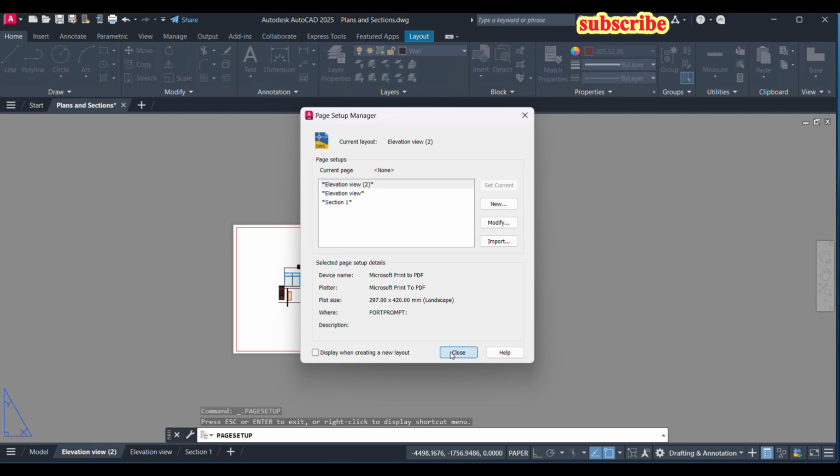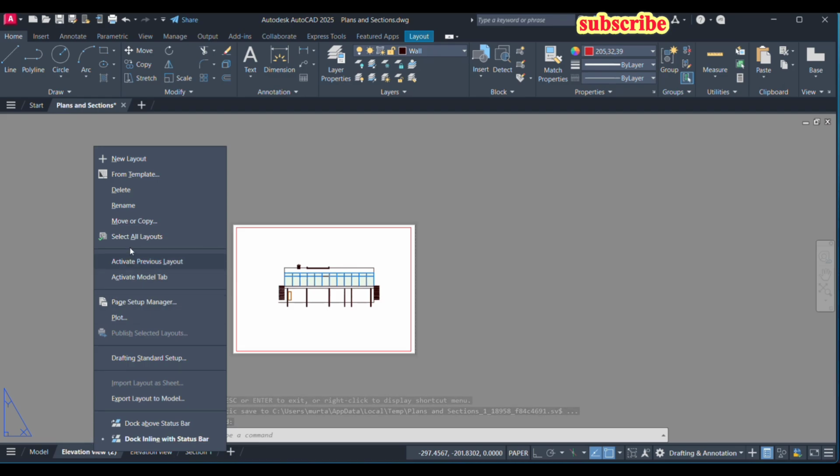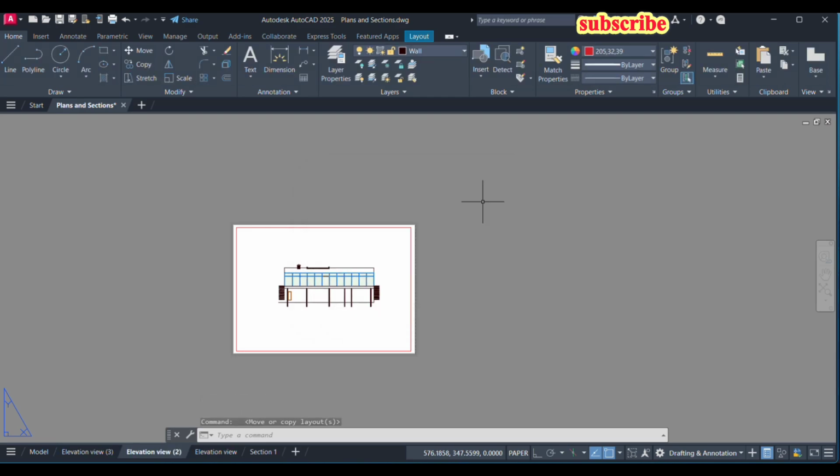So we close this view, and here we want to copy the view and rename it to be a plan view. Currently it is elevation view. We click on move or copy, and here we create a copy of the elevation view. So we click on OK, and here we have a copy of the file. So we can change this to be plan view.